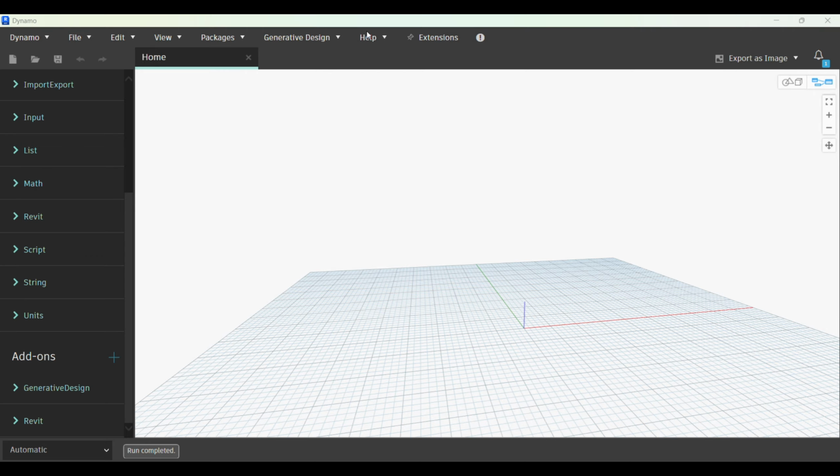And the next thing is our execution bar. Can you see we have an option here about automatic, manual, etc.? So this is called the execution bar. We always usually keep it at manual, because whenever we create new nodes, when this is set to automatic, the node gets executed and the script starts working. So we don't want that. We want to run the scripts whenever we want, on our command, right? So not automatic. We'll just select the manual here.